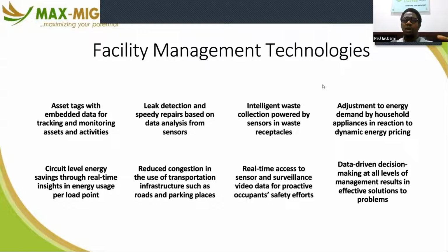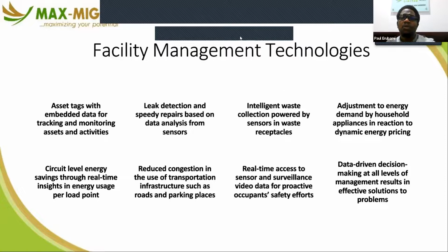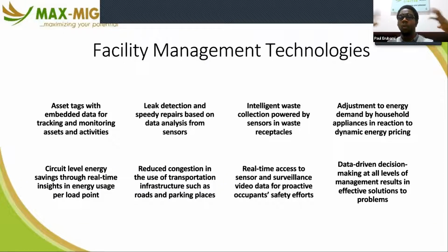So there's often that overcapacity in power plants, so that if they run on a consistent rate of production, then we will be buying 80, 90% or even 100% of what they are producing only for 2 hours. And then they will keep running and will be buying just 20% of what they are producing in off-peak hours. So when they create dynamic energy pricing, they encourage you to move certain loads away from peak period. So that's where they don't have to provide capacity for what is currently peak, because what is currently peak is a lot of loads that shouldn't be running at that time, running at the same time.